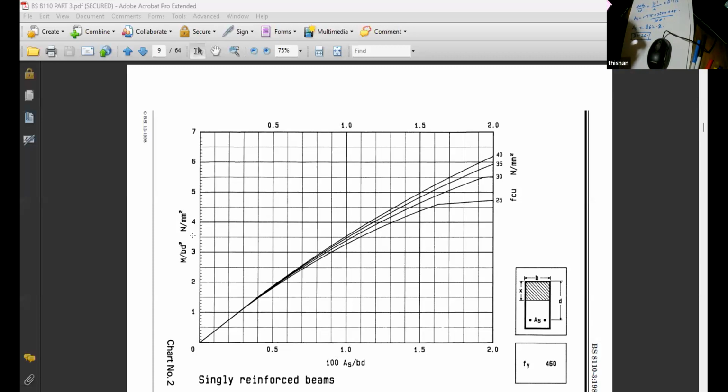Yes, sir, there are a few. One is, if we use welded mesh for a floor slab, what is the deviation from normal codes? No, nothing. It's a construction practice, because the welded fabric is made to a standard. So you just put it. The only thing is you have to make sure the steel area is there.